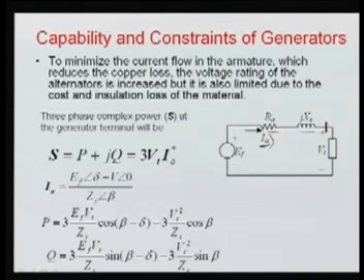So it is 3 times the phase voltage multiplied by the current which is flowing here, and that is the conjugate of this. So we can write this current IA, the armature current, as this voltage minus this voltage divided by the impedance. So we have written here EF, and here we have written the delta. Taking this voltage as a reference, we have seen that this EF is having some angle delta.